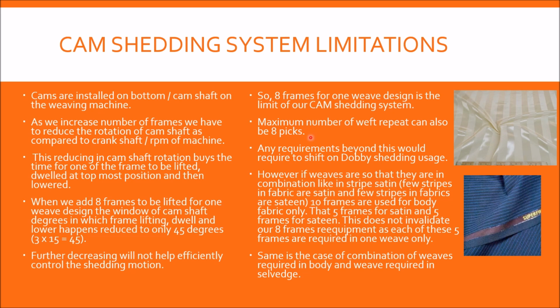Generally, we have straight draft and basic weaves like twills. So that is why, when we have 8 frames, we can insert a maximum of 8 picks repeat. So repeats of wefts are similar to the warp repeat generally. So weft repeat is also mentioned over here.